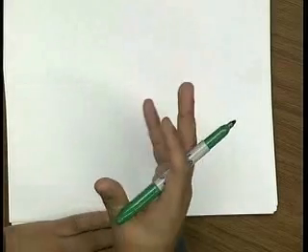And in a real PLL, what you get is cycle slipping. For a period of time, loop gain is positive, you go in the wrong direction, but it's a self-correcting mechanism. So even if you start out in the wrong direction, it will slip into the right phase. And again, I should emphasize, it's a very nonlinear circuit until you get the phases very close.